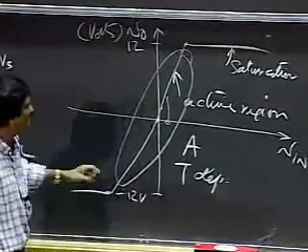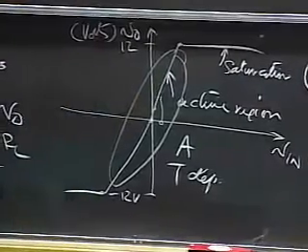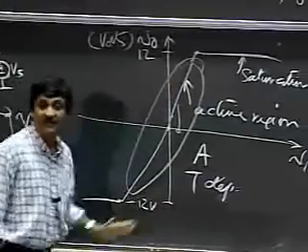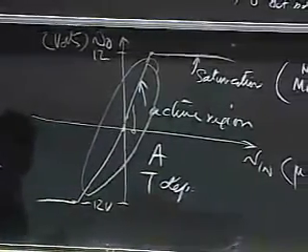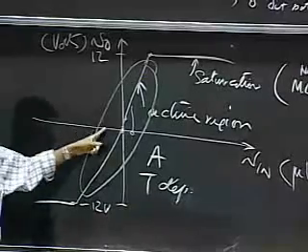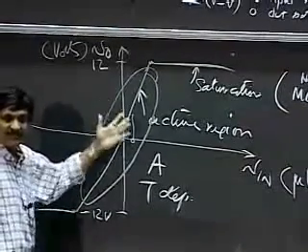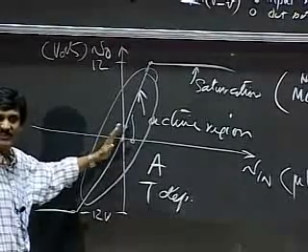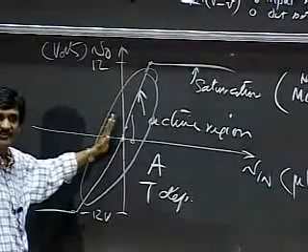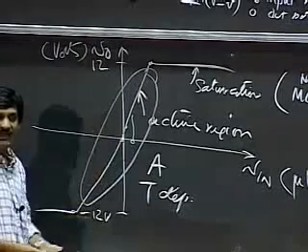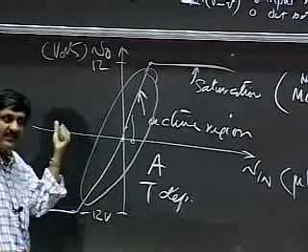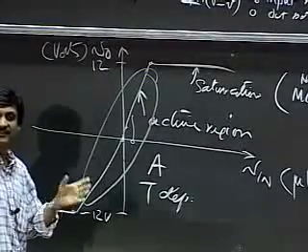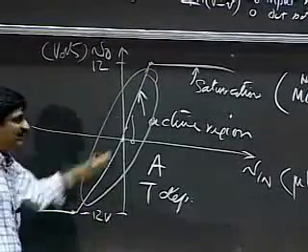So let me show you an example. I'm going to show you this curve for this amplifier, applying an input and plotting the output. Then I'm going to use a heat gun to heat the op-amp, and you're going to see this vary all over the map. Some of you may remember from last week a similar situation, where the gm for the MOSFETs you were given was also dependent on temperature and so on. It's a very common occurrence, and that's certainly the case for the MOSFET.